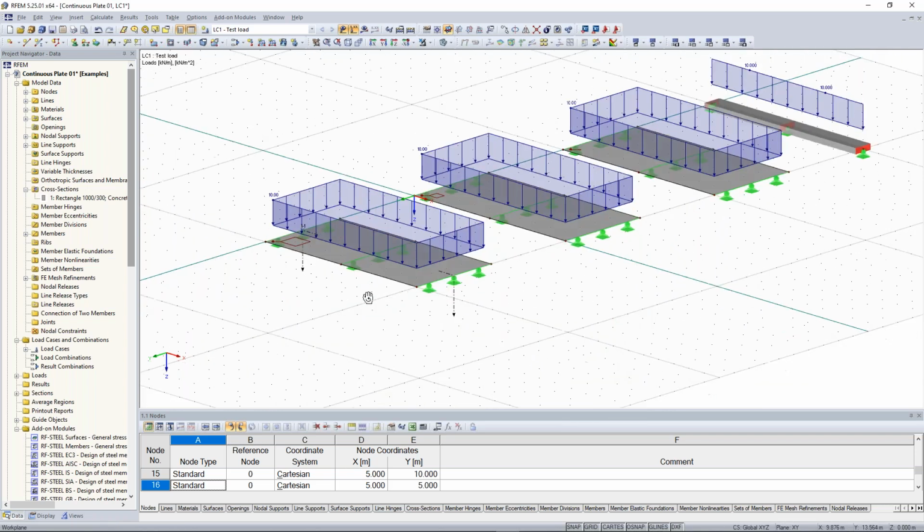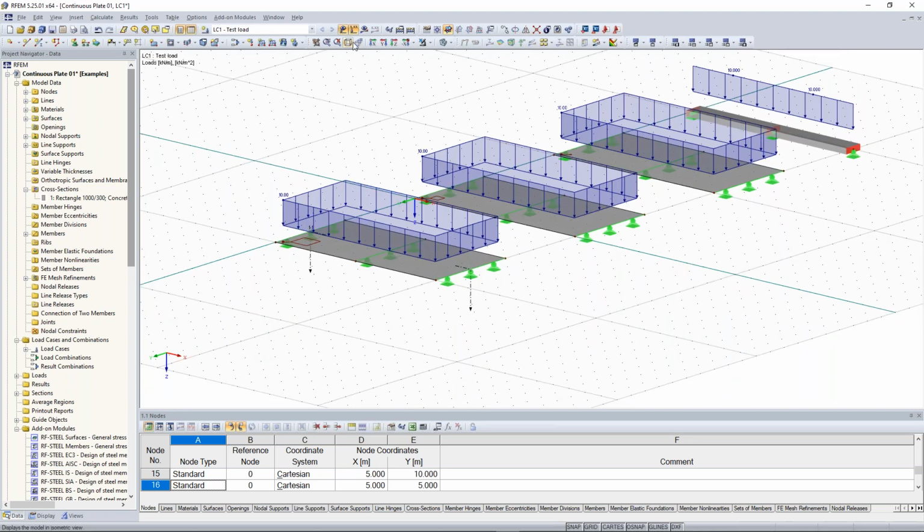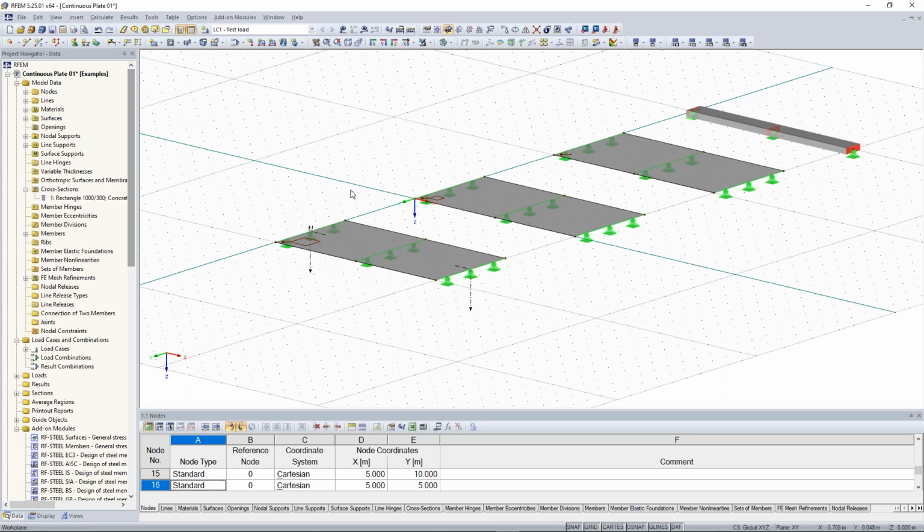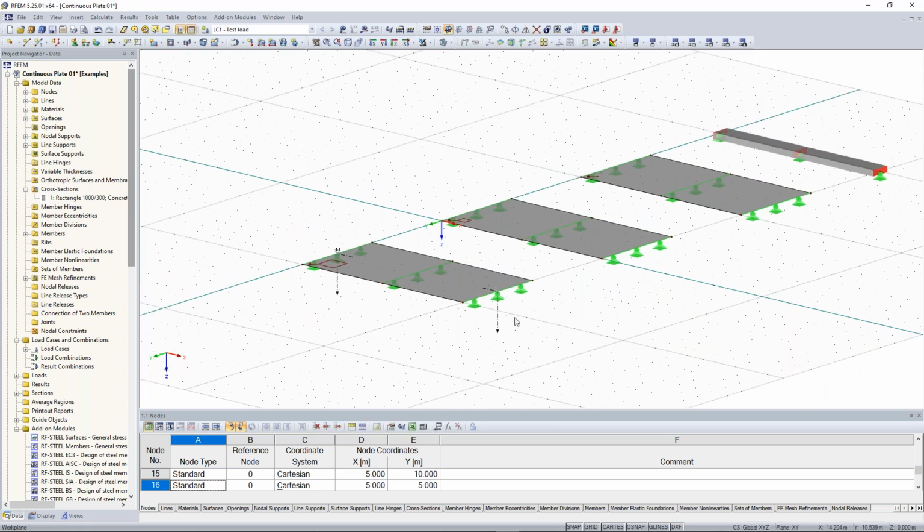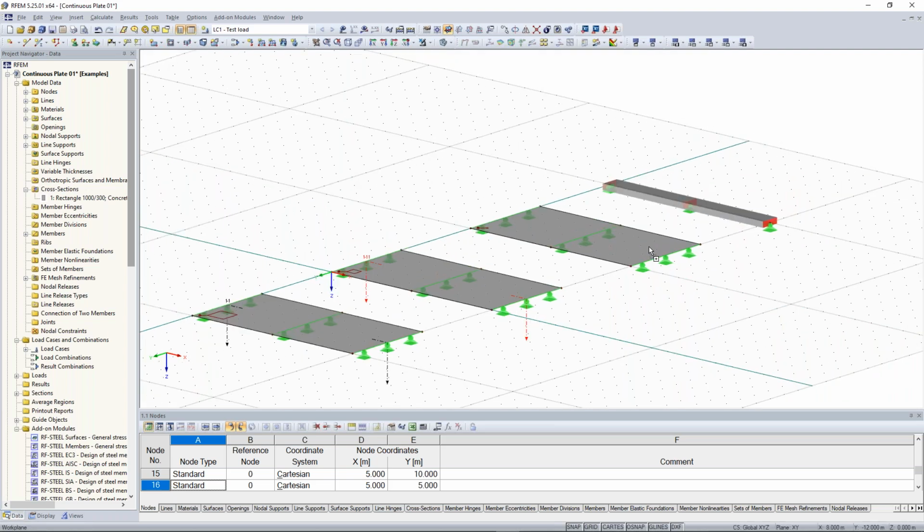Now I see here the section. Maybe I can disappear the loads here by clicking not to show the loads. And now also one of my favorite ways of creations or something like that in RFEM is drag and drop. So press Ctrl key, left mouse click, and copy it from one side to the other. So from one surface to the other surface.